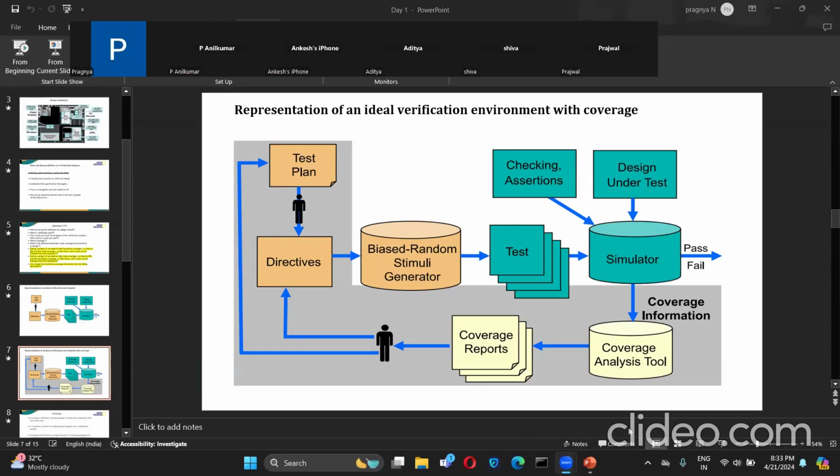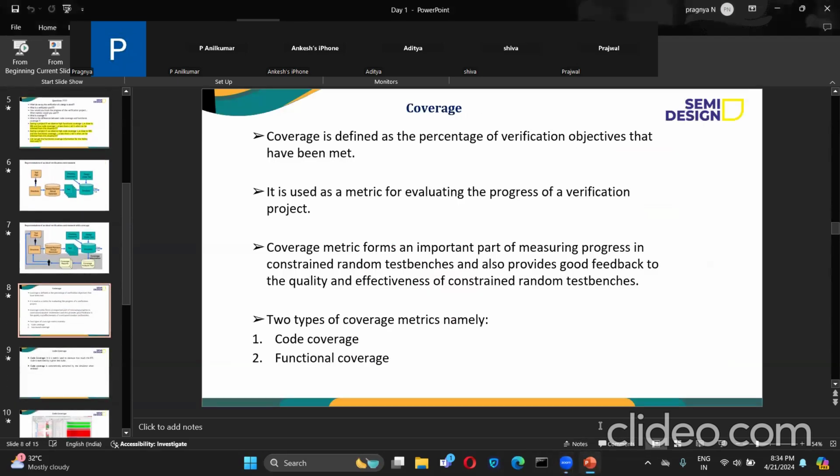Basically, my question is, can we capture the coverage or not? No, right? When the functional coverage is not done, you can see what bins are covered, that is fine. But the coverage information is not captured because that functionality is not covered, right? Already it is showing that at the functional coverage level, it is not covered. That's why we cannot get the proper coverage analysis. That's why it is recommended to run a regression suite. Once everything is passing in the regression suite, then only we go for the coverage analysis. Okay. So this is also one of the important questions we should know about coverage. That's why I have asked.